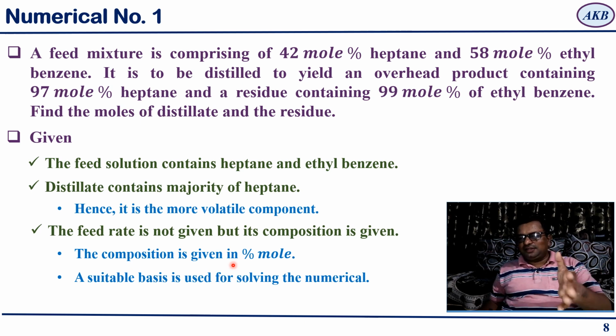Composition could be either mole percent or weight percent. In this case, it is mole percent. Even if it is given in weight percent, you can convert it to mole percent. In coming lectures, we will be discussing how you can convert weight percent into mole percent. So the point is, whenever the feed rate is not given and the composition of the feed is known to us, you start with a suitable basis, which is used for solving the numerical.